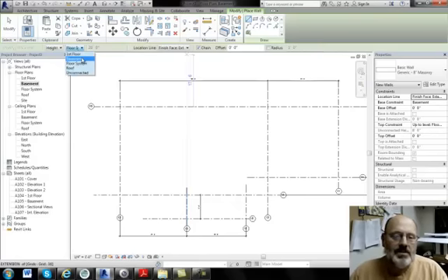You can't go from basement to basement. I am in the basement level. I'm going to constrain them to the floor system. So they're going to go from the basement up to the floor system, which they're supposed to do. And they're not going to be 20 feet tall. This is ghosted out now that they're constrained. Here I can see over in the wall properties that the base constraint is the basement. They're going up to the level floor system, unconnected height 8 feet tall.